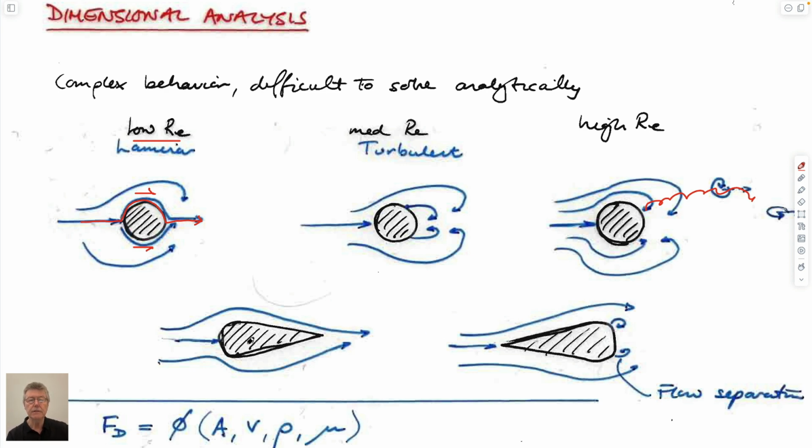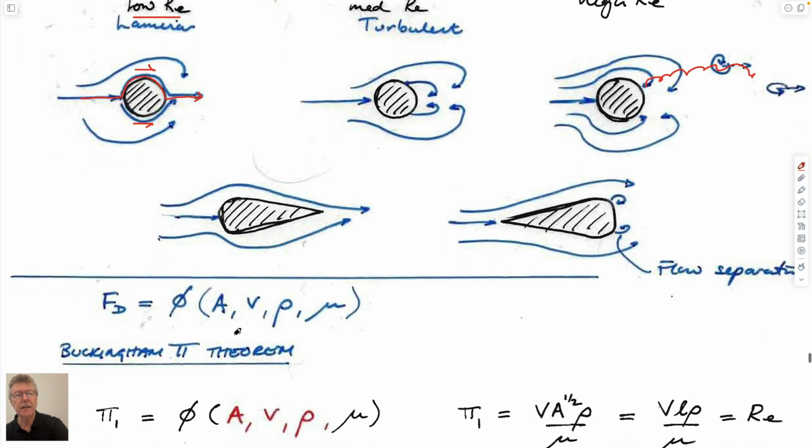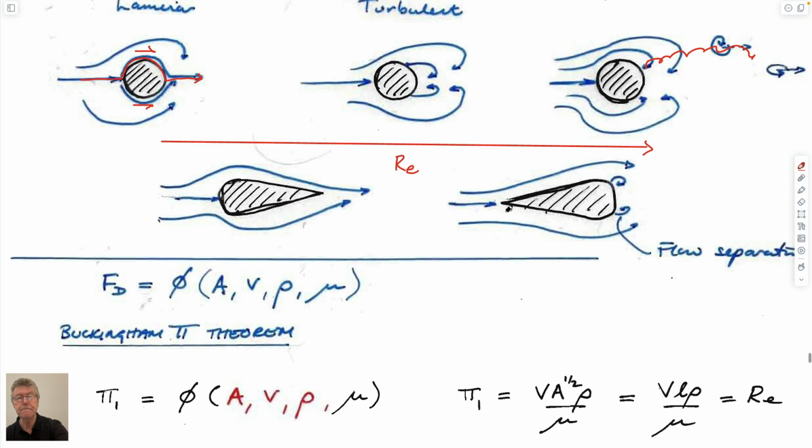And I guess to be efficient aerodynamically, you'd prefer to have flows which don't separate, and that's why people wear these helmets in the sprint in the Tour de France, which are surprisingly blunt on the front, but tapered at the back, so you avoid the separation and therefore the drag that occurs. So it seems clear that we want to know what the Reynolds number might be in those particular cases to be able to classify those flows.